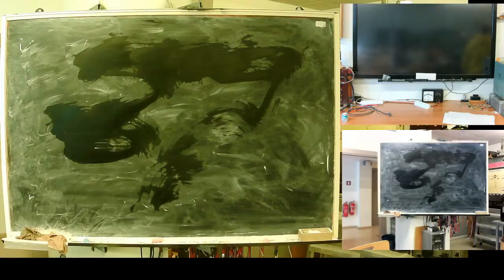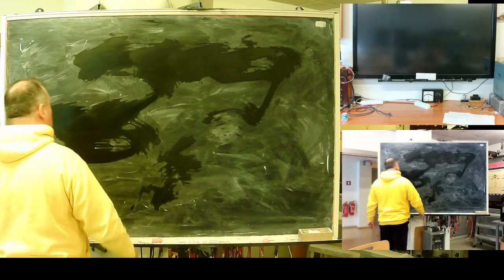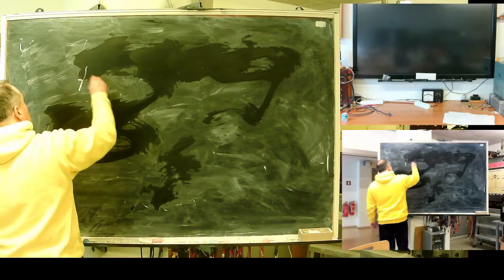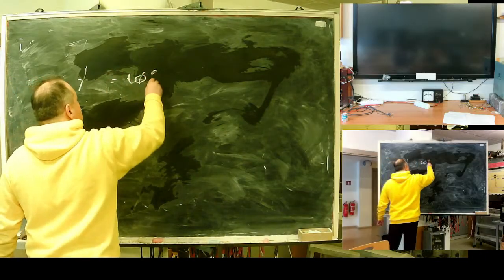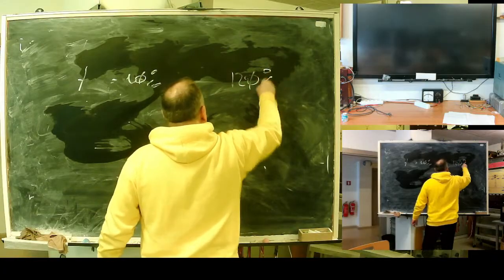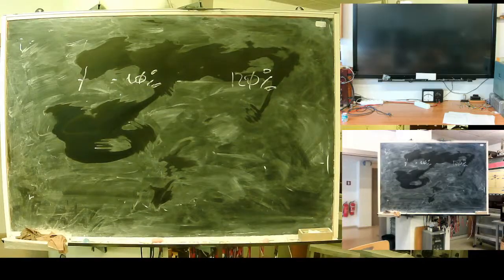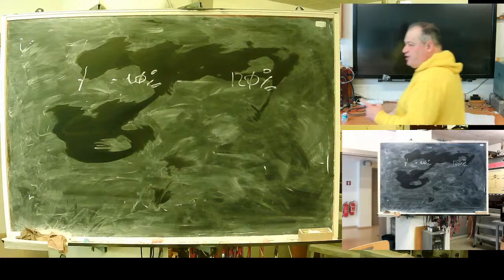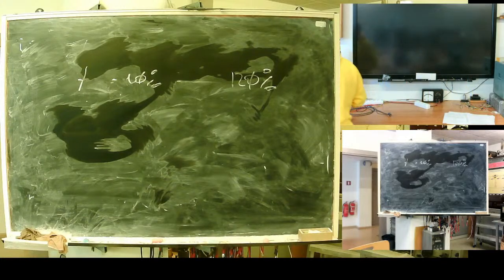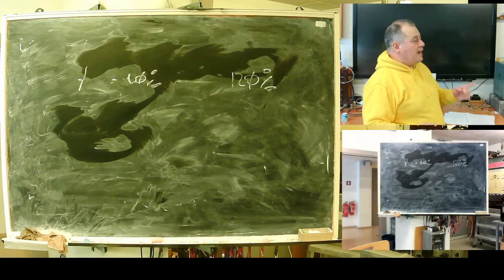For hydro turbines, the working frequency range is from approximately 10% of nominal up to 120%. It's the working allowable frequency range for a hydro turbine. Same thing with some wind turbines, though not any wind turbine can operate in such a wide range.